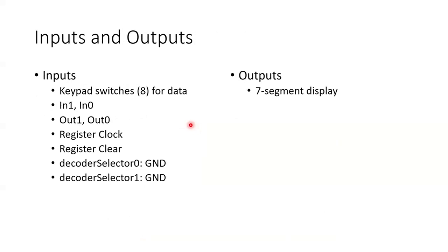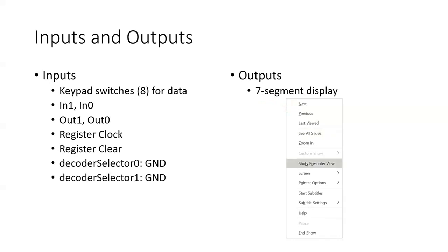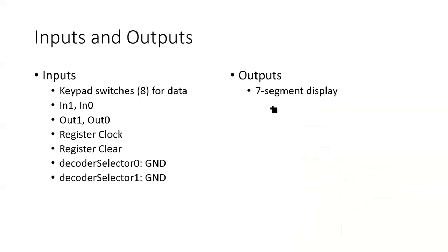All right, now in total you have several inputs, but the only outputs that you have are just the 7-segment display outputs, which are 24 outputs, out of which let me write it down. So you have 24 outputs, which is 23 down to 0, out of which you are not connecting bit 7, you're not connecting bit 15, and you are not connecting bit 23, because if you remember, they were the padding bits, right?